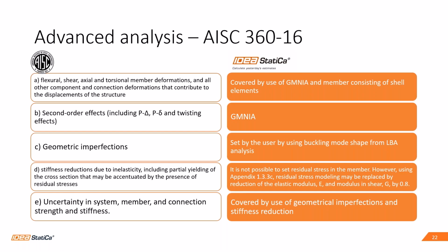However, you can model those by reducing the elastic modulus. Okay, so that is allowed by AISC, so you can go into IDEA StatiCa Member and reduce the value of the elastic modulus. Okay. And finally, the last point is covered by the use of geometrical imperfections and stiffness reduction.